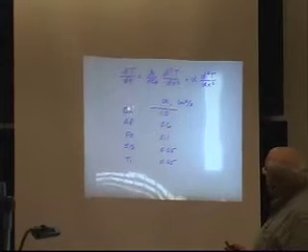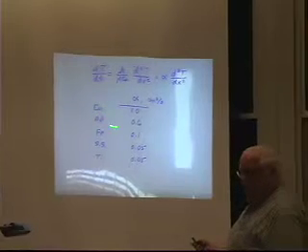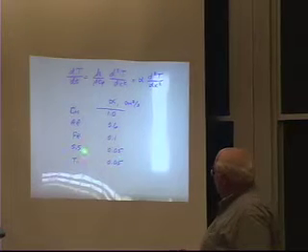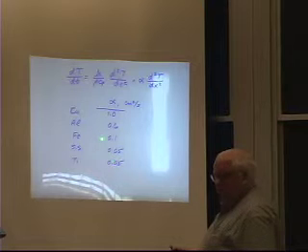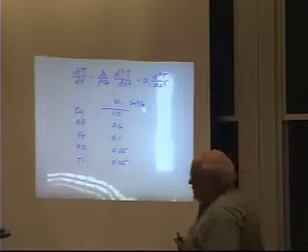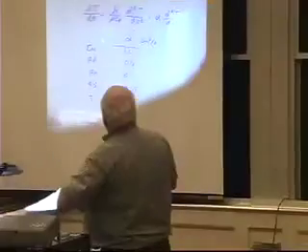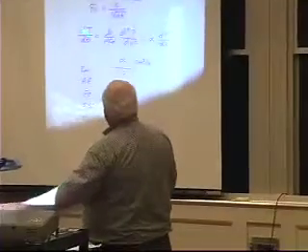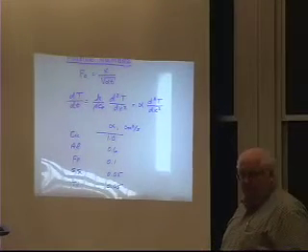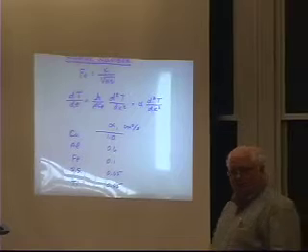Okay, we know we put copper and aluminum on the bottoms of cookware in order to transfer the heat better, right? And that's because steel and stainless steel have very low thermal diffusivities. Thermal diffusivity just comes out of Fourier's second law of heat conduction, which is the change in temperature with time. So this is transient heat flow, equal to K over rho C sub P times grad T. Now that you guys know what a grad is, right?